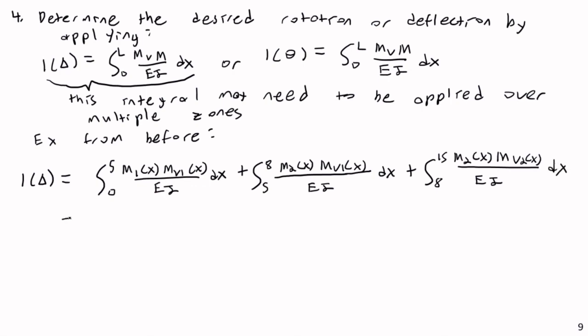As a note here, we do have to watch our units. This is the easiest way to screw something up with this method. Like a lot of things we do in structural analysis, it's very easy to screw up the units. If I wanted to keep this integral unchanged, with my boundaries in feet, I would need to convert my E from 29,000 KSI to KSF, kips per square foot, and use moment of inertia in feet to the fourth power instead of inches to the fourth. Or I could convert my bounds into inches. The whole thing is we must always use compatible units in all cases.